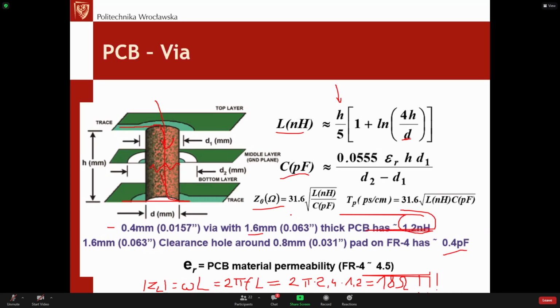Sometimes we have characteristic impedance calculated. That's especially critical when we try to make 50 ohm or 25 ohm controlled impedance lines. That's for higher frequency. When you make a PCB design for higher frequency, that's something we play with. But frankly, for controlled impedance traces, we usually don't use vias at all.